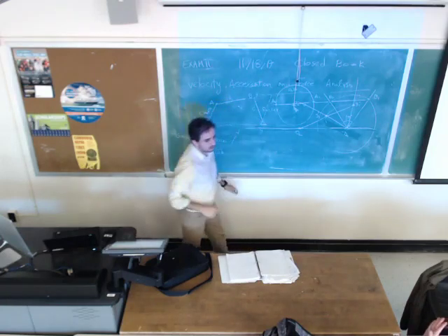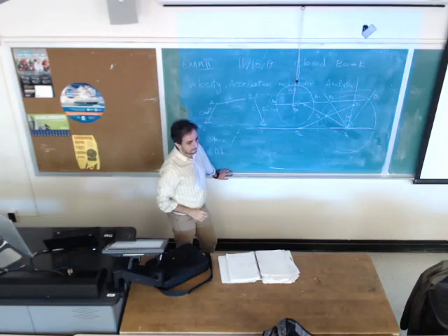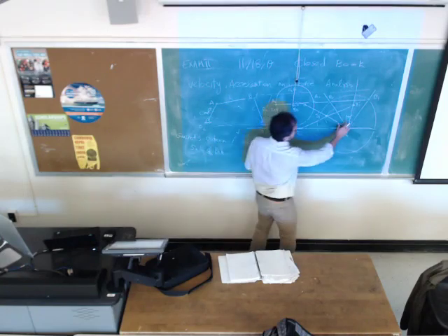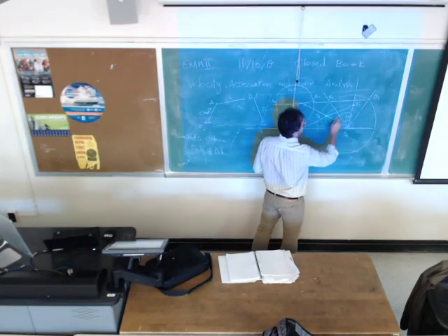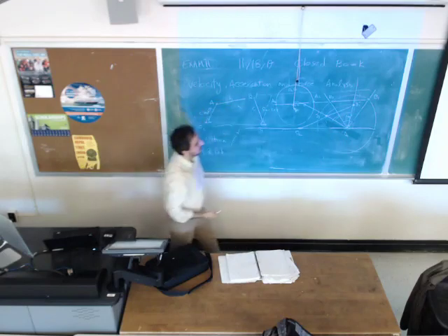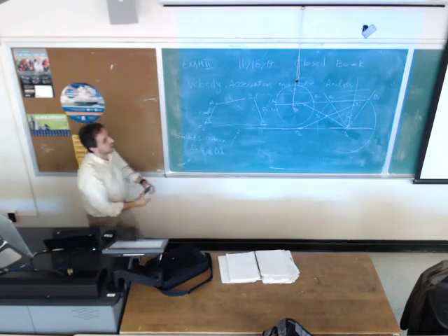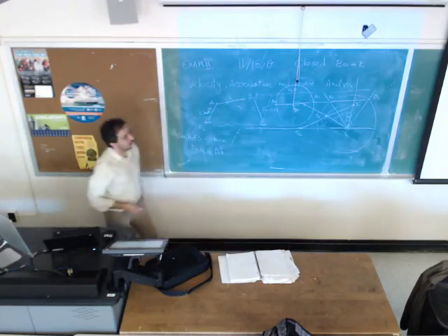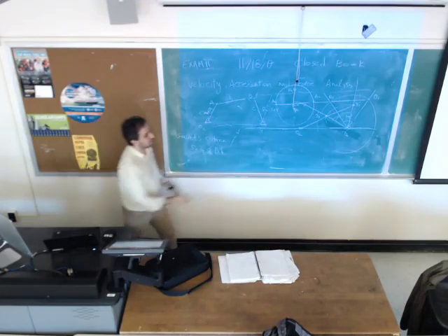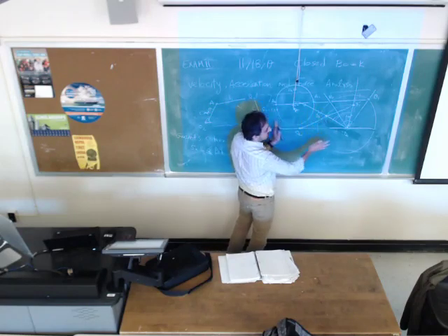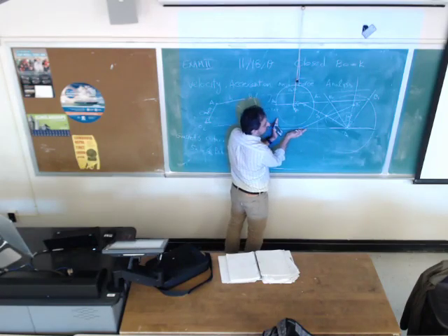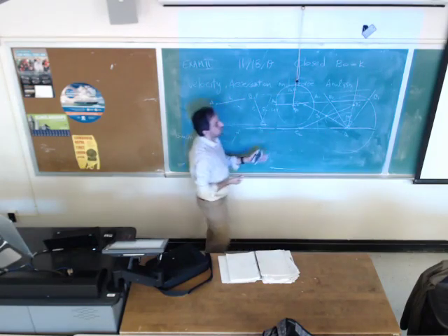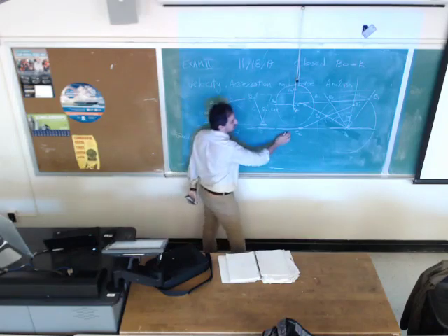But the line B2 is dependent on B1, right? Because we have the construction of 45 degrees. Yes, this is what we want to have. This angle should be almost always 45 for this problem. Everybody can see how I can play with the free choices to satisfy the design criteria. I have a restriction: I cannot move the O2 from the line passing through O4. So I have to satisfy this restriction.